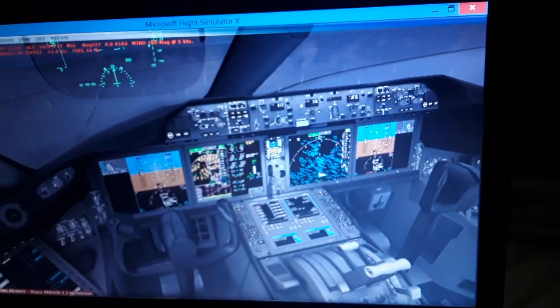We input the runway we're going to use for takeoff, Zurich International 114, the runway length, the runway slope, the wind direction and speed, the barometric pressure, the density and the temperature of the air, and also the runway conditions, whether dry or wet. And we have the takeoff speeds, the V1, V rotate, and the V2, which is the initial climb speed after takeoff. So you can see here, the initial climb speed after takeoff.